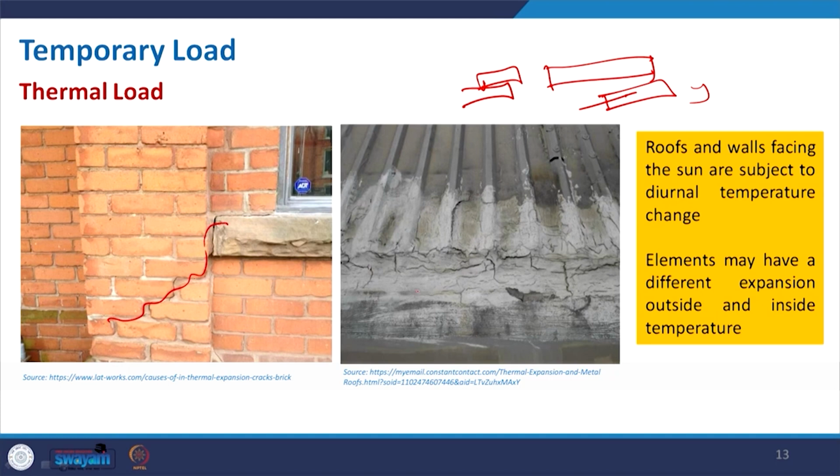This is the brick, and this is roof tin based, and there is some putty which was fixed initially, and due to different expansion with heat, here we see the cracks. So, the purpose is not fulfilled here, because if it develops cracks, sometimes it may also be prone to water leakage, and then your building will get damp.